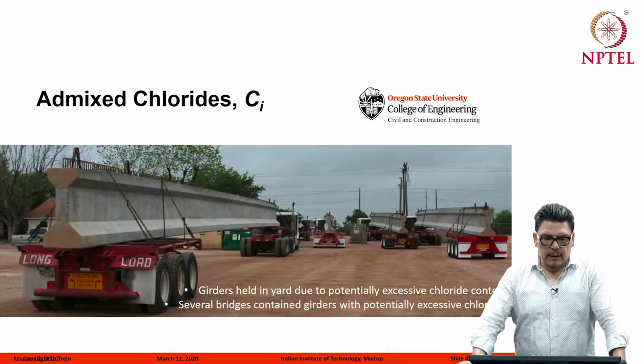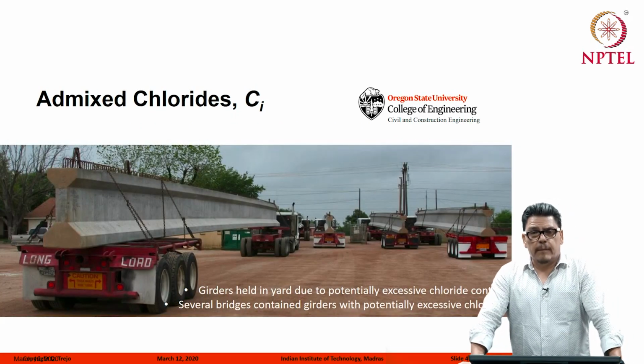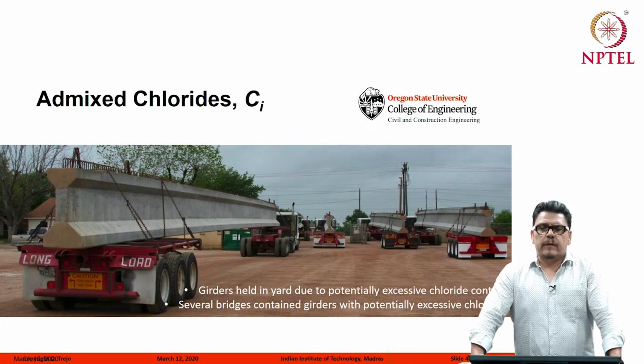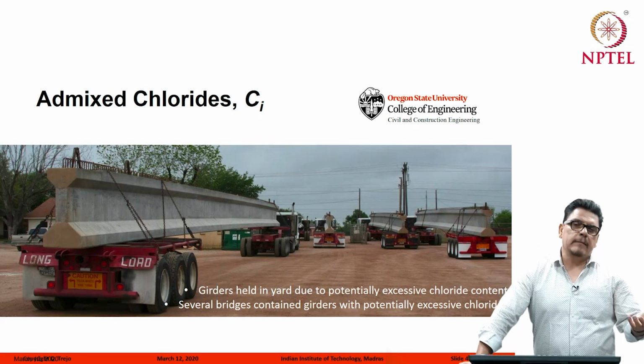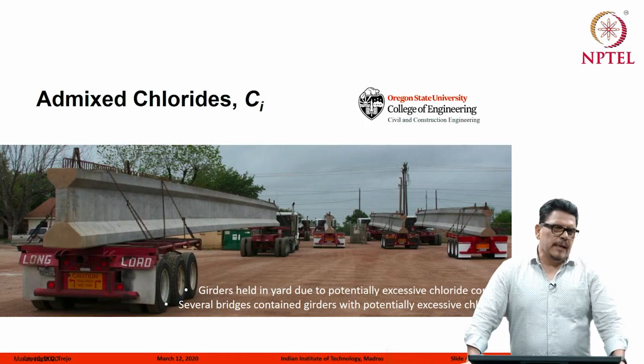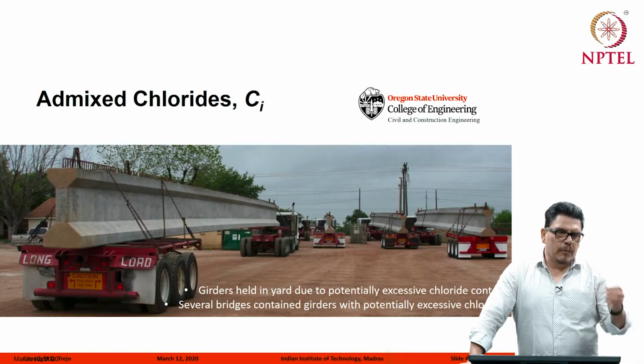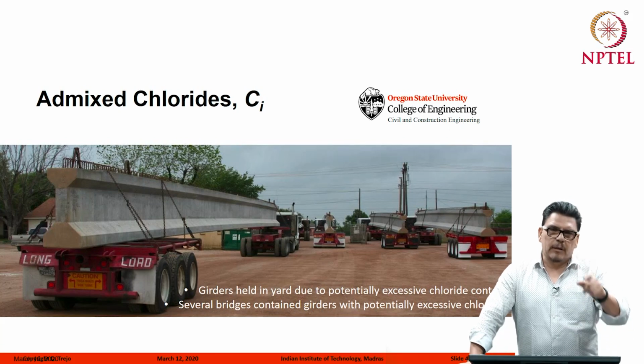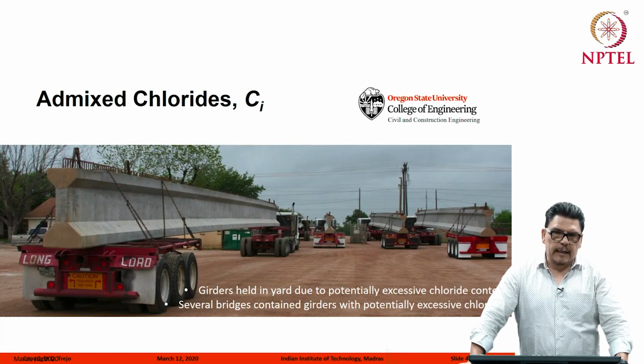And so the question is, again, which is correct, and does it really matter? Well, I'm going to make a point here. It does matter. These girders here were produced, and what they did is they changed the water source. After several months, they realized that the water source had a high chloride concentration. So they did some testing, and they found out that one test was passing and one test was not passing. You think, well, okay, no big deal, but the fact of the matter is if you don't pass this, these girders have to be thrown away. There's a significant investment, a significant cost, in the millions of dollars and maybe tens of millions of dollars.